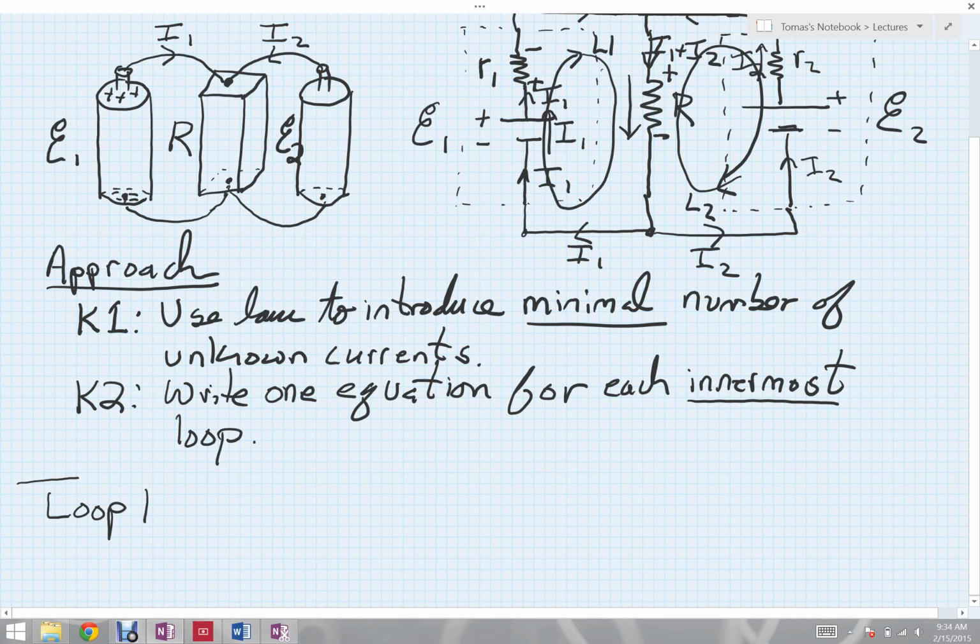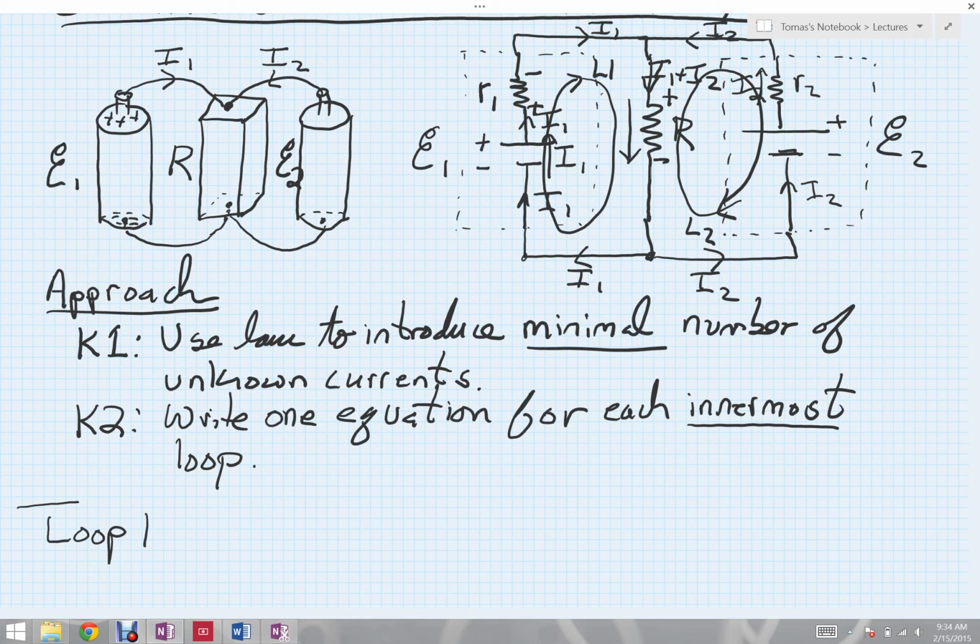And similarly, as long as I'm at it here, if we look at R2, the current is flowing upwards through here. That's the sign convention we chose for that current. So this will be the upstream side of resistor R2. That will be the downstream side. Okay, now with those labeled, we're ready to do our loop equations. As usual, I always like to mark my starting point here with an X so that I don't go too far around my loop, and so that I actually do go all the way around my loop. So let's now write this particular loop equation.